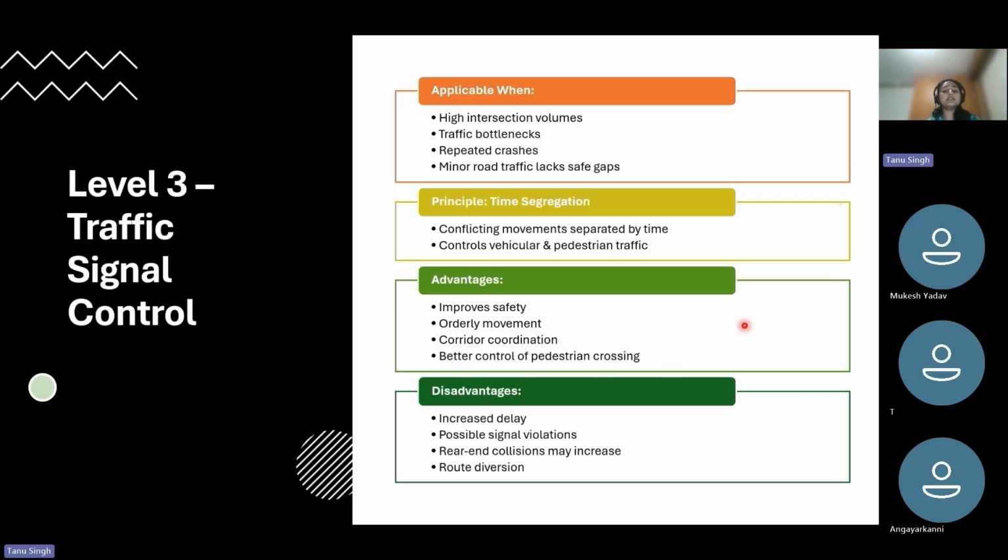Now coming to the disadvantages. They introduce delay because movements are not allowed simultaneously, as in the case of roundabouts. There may be signal violations, and sometimes rear-end collisions increase. Drivers may even divert to alternative routes to avoid signals. So these are the disadvantages of signal control.